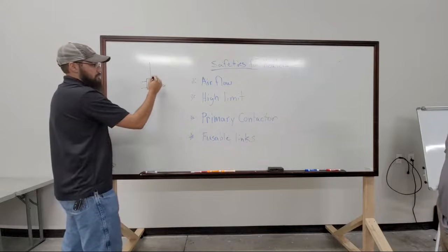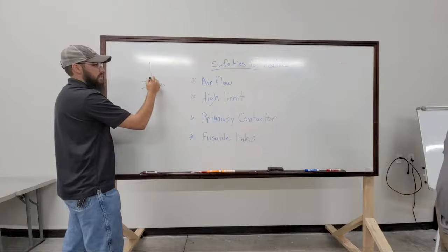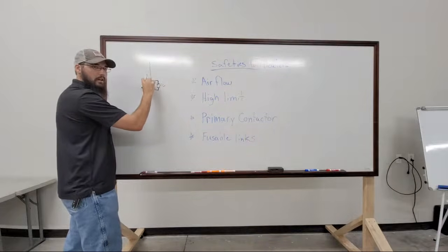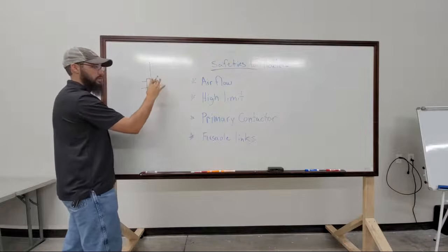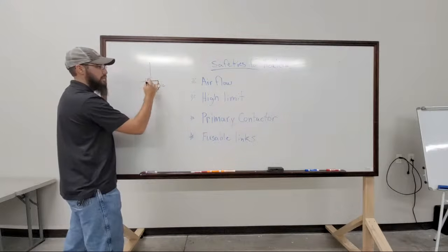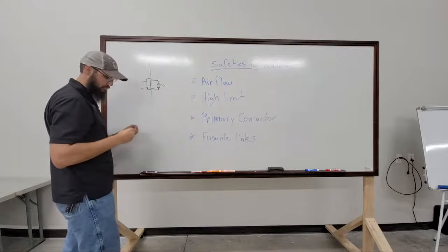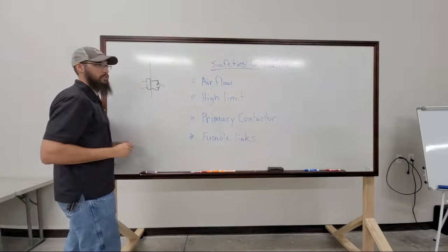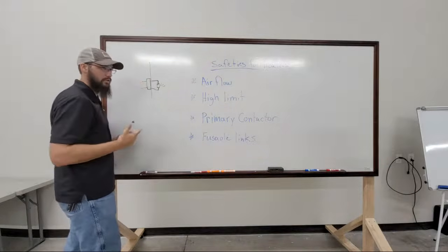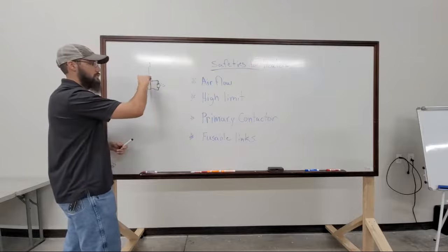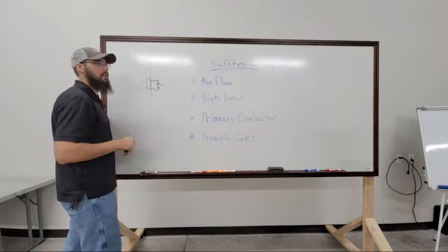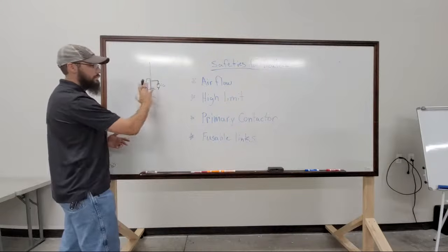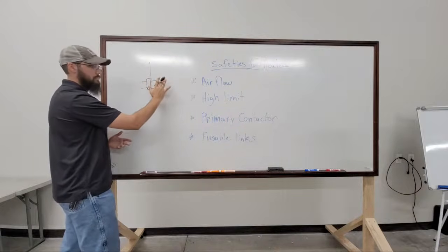And yet, some of them you can replace without having to replace the whole ceramic. A lot of them you end up replacing this whole ceramic piece. So they come both ways. Another field term that some of my more old school techs use is a teardrop safety, or a teardrop limit, because the general shape looks like a teardrop, but the fusible link is the proper term for it. So if you've got an older building, don't be surprised if you run into that.